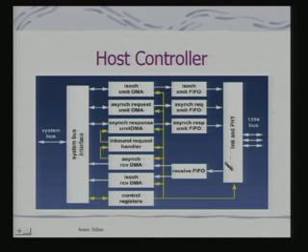This is really the interfacing hardware, the physical as well as the link layers of 1394, and typically this is what is to be always powered up, because even when the host, maybe a PC, is not on, the data communication should take place, so these signals should be powered on. And this interfacing is what is interesting and should be noted.